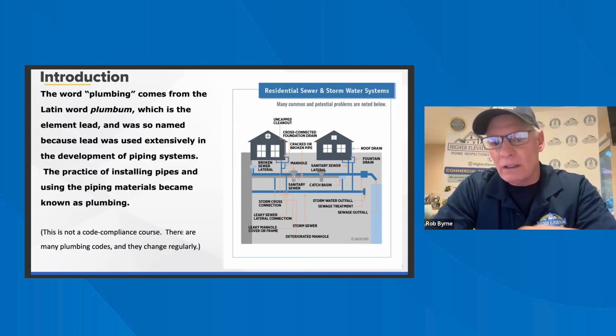Water heater general comments, that's pretty straightforward. Most tanks are insulated steel cylinders with enamel coating on the inner surface. They are referred to as glass lined tanks. The lining helps prevent corrosion. Conventional residential water heaters have life expectancies that vary greatly. That's why we personally do not put life expectancies. You can if you want, but I think you wind up with a situation that you might not want to deal with.